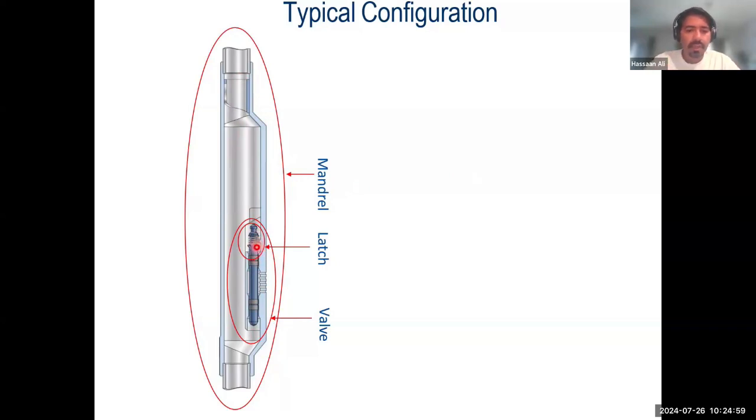because of the pressure differentials, the different annulus and tubing pressures, they can result in the movement of the gas lift valves. And we do not want a lot of movement, because too much movement can actually push this valve out of this pocket. So we want some sort of a device to securely latch into place. The gas lift latch is essentially that device.